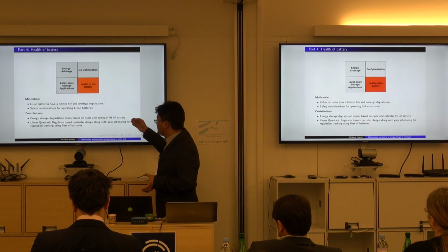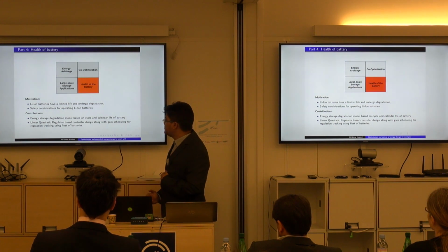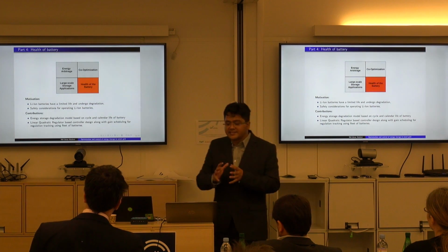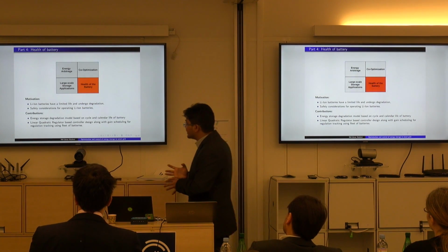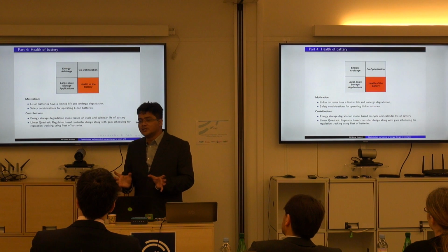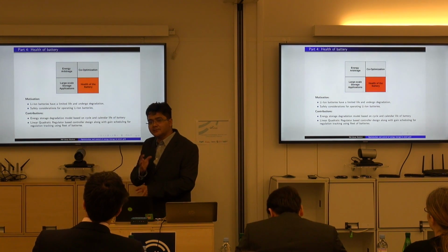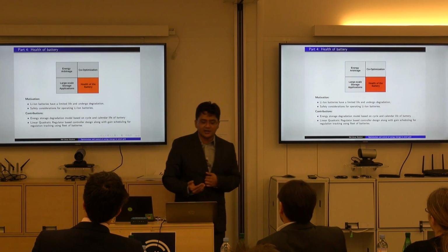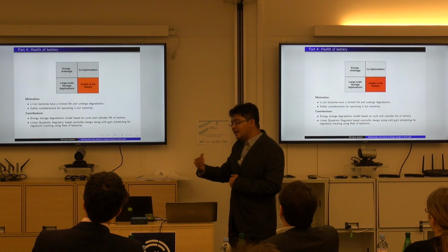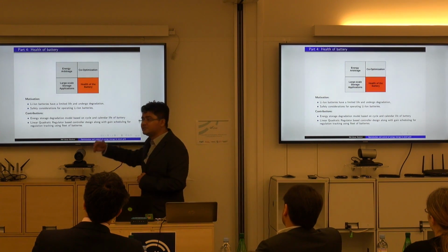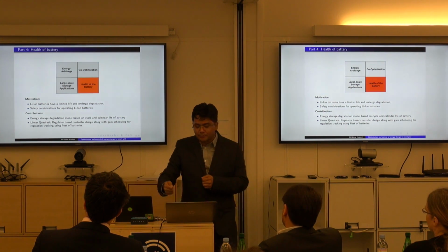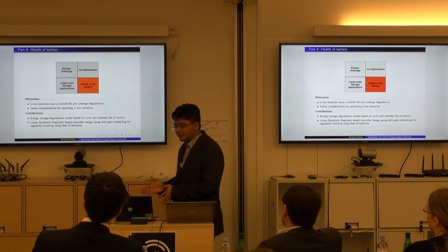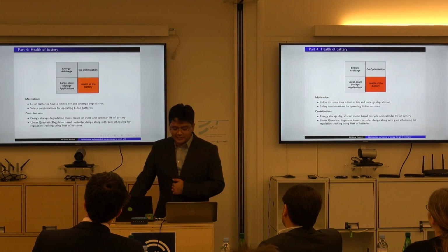We have a bunch of publications which are already described in this part, and the second contribution is considering not just one goal of tracking the regulation signal, but two goals: maintaining the SOC of the fleet, and at the same time tracking the regulation signal. So we propose an LQR based controller design, and furthermore we add an additional layer of gain scheduling which gives more importance to maintaining SOC if the SOC drifts farther away from the desired set point. So that's all from my side.